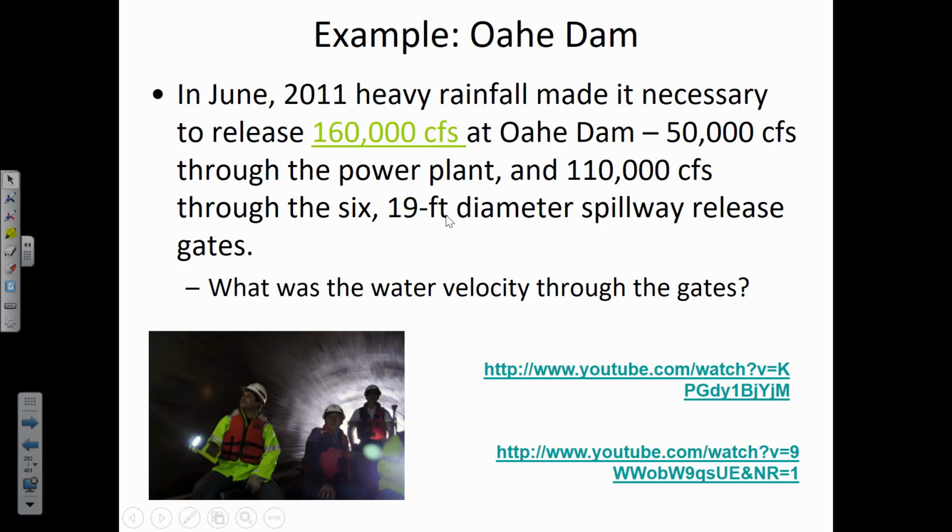That's right. It could erode the soil. There could be scour. And sometimes they'll have a specific location where there's an overflow spillway that's armored with concrete, and there's a lot of riprap at the bottom to try and dissipate the flow. And so they anticipate the possibility the reservoir could fail.